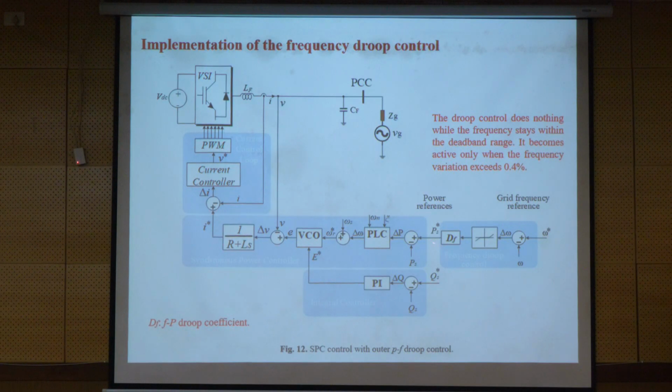So for example, assuming that we inject 10 kilowatt, and then the frequency drops to 49, it means that our frequency is dropping, then the coefficient provides the value to P and increases it. So it says that, instead of 10, now you should go to 11 because the frequency is dropping. Okay? So by this, we can provide the P reference based on the situation of the frequency, and we can somehow regulate the frequency of the grid.